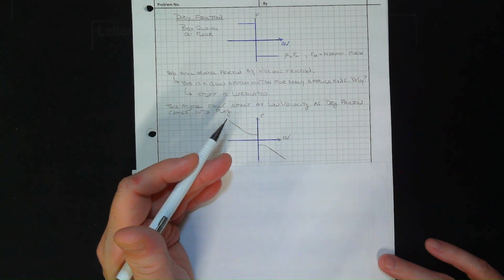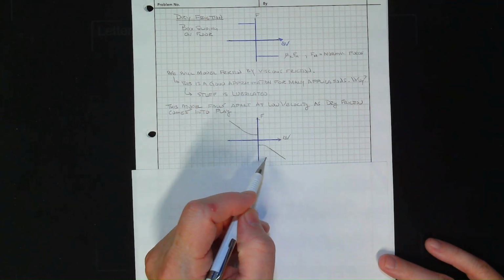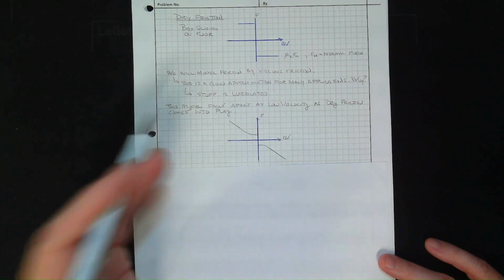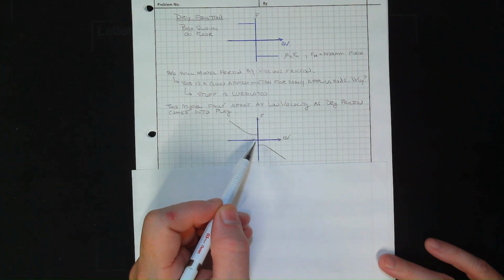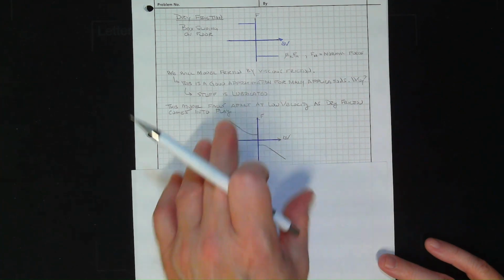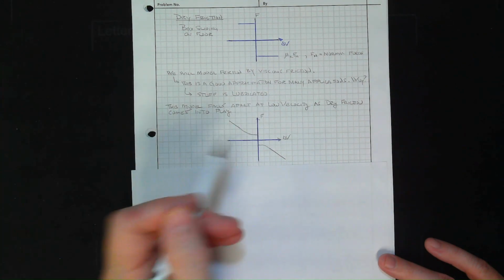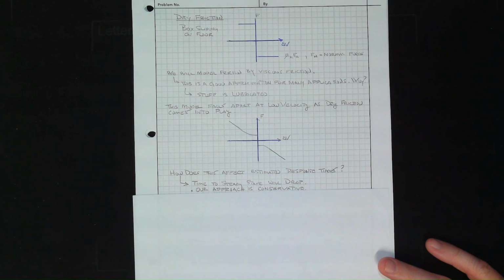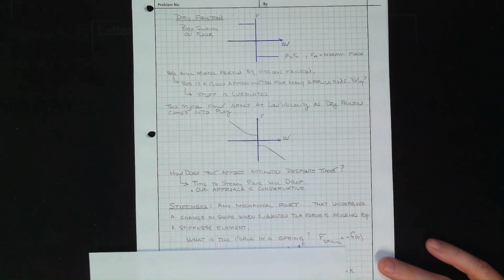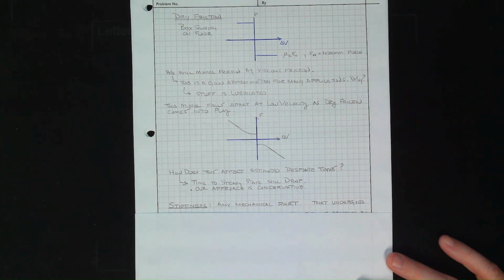So when you're projecting something will settle in 1 second because of this kind of effect, maybe it settles out in 0.9 seconds. So it's a more conservative situation. We're not modeling this, but we don't need to. If we get acceptable performance based on our specifications, we can expect that it'll settle out a little bit faster. So that's not a big problem for us. All right, so that's what we're discussing there. So we've dealt with damping.